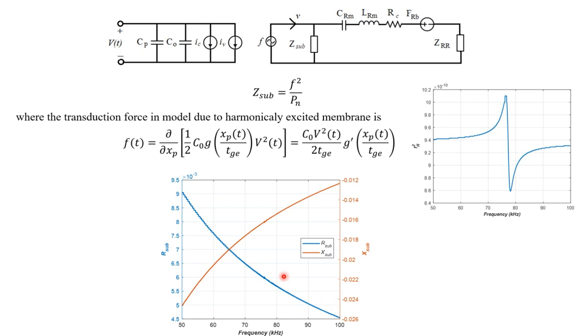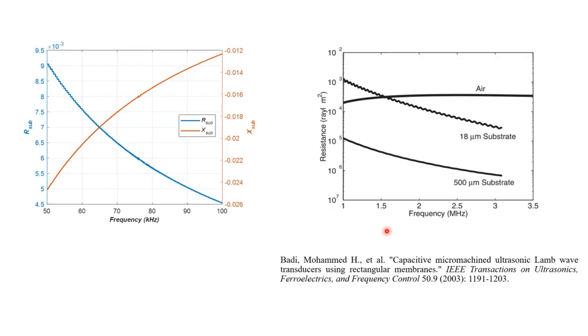And when you measure the impedance of such thin substrate cells, you see in the measured real part of the impedance data that you have dropping characteristics, or the real part of impedance decreases with frequency. While the susceptance, or the measured reactance, is growing with frequency, and that is typical of CMUTs, which shows a capacitive load. So this is also reported